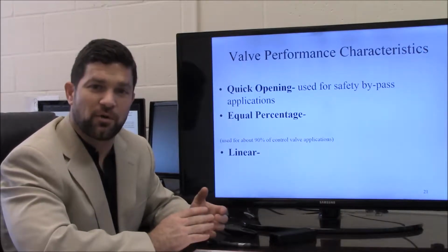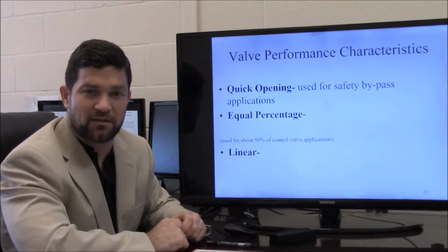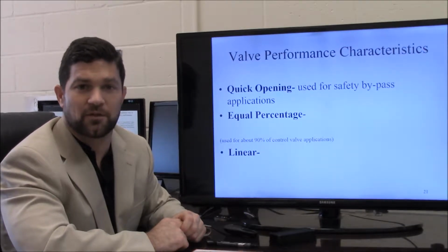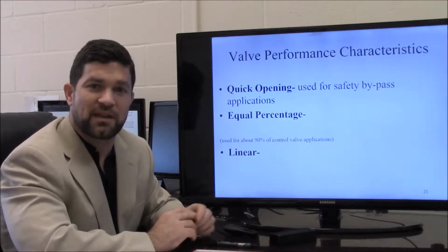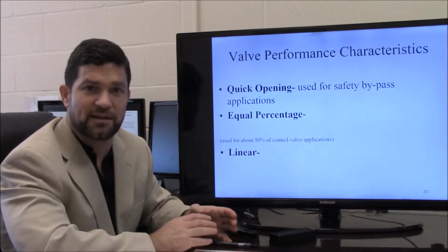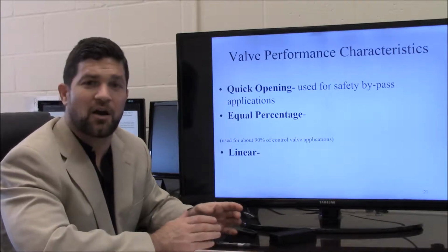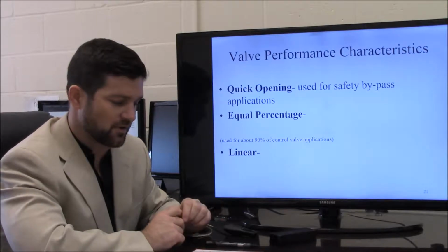The first important point is that the size of the equal percentage, or the size of the linear valve, is going to determine the maximum flow that goes through the body, the valve body. So again, the primary thing that we need in terms of designing a control valve is we need a valve that's big enough to accommodate our maximum allowable flow, and that will be something that's fairly straightforward to determine.